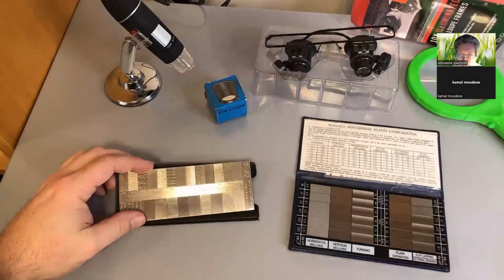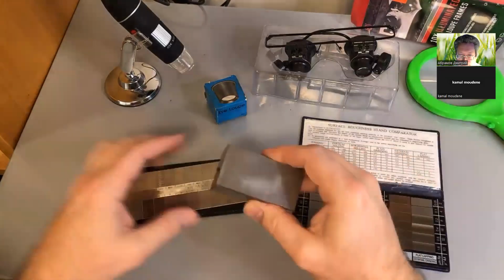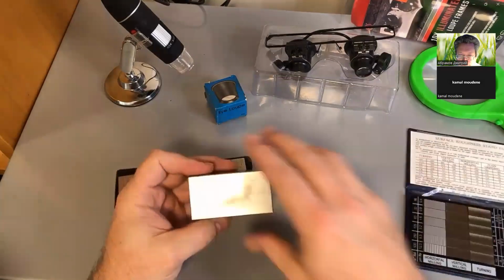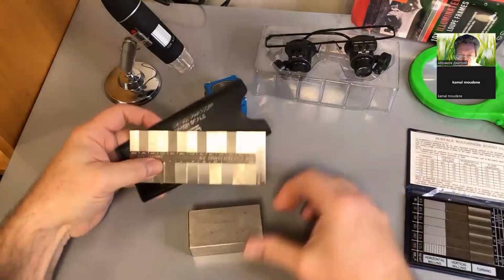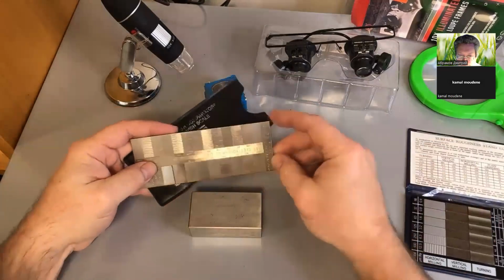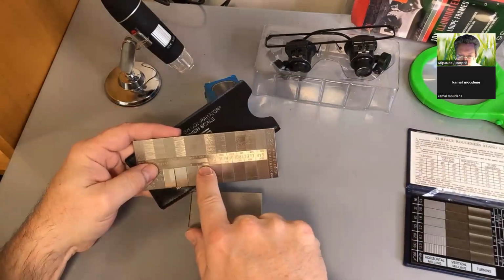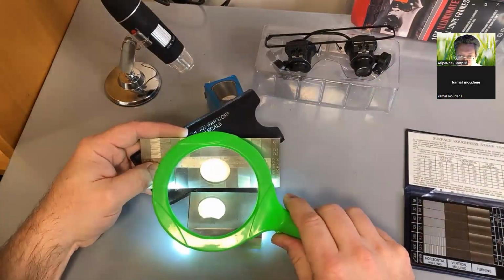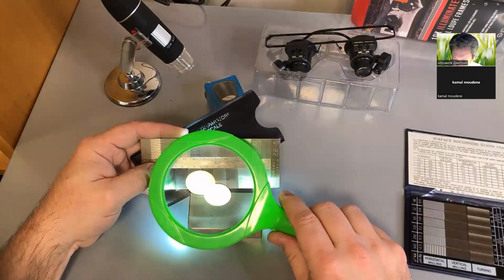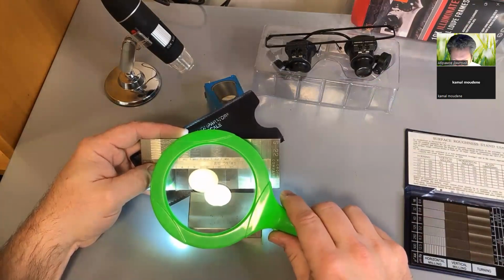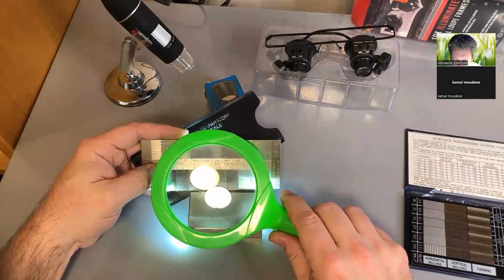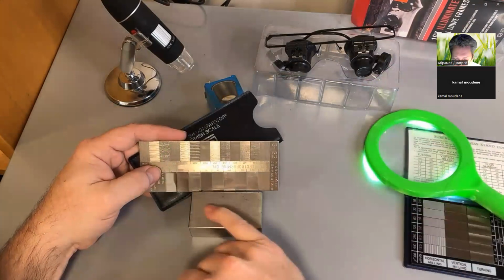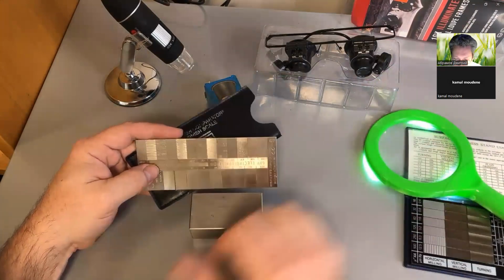So let's take a look at a specimen here. So I turn around and I have a block that's been ground. So I want to see what this actually is. So what I would do is I would hold my piece up against here. I would go down to the ground symbol here, and I would look at it and I would say, I only have two options for ground surfaces here. I got an 8 and a 16. Neither of them are as fine as what I have ground on here. So it's going to be less than an 8.